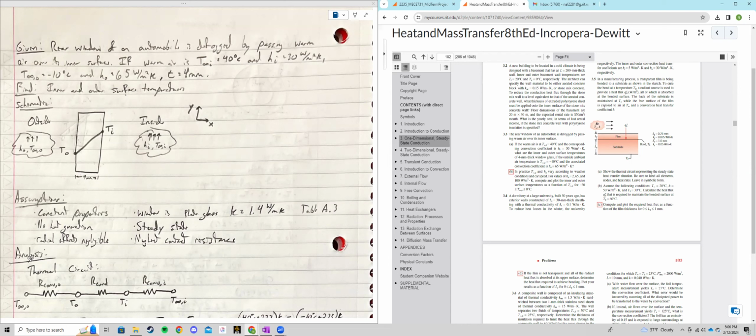So, hopping into the analysis, we can see that I have drawn the thermal circuit for this question. Starting in the outside area, we have T infinity,o, which then hops into some convection, which we have labeled as R convection,o. And then we first hit the temperature of the outside layer here. You can see it matches up with the drawing. Following that, we have conduction through the material. So that has been labeled with R conduction, which is then going to lead to T_i, which is the temperature on the inside layer.